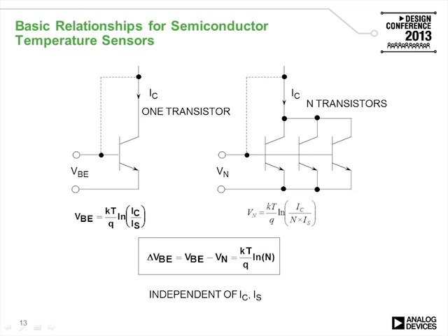A silicon temperature sensor is actually quite a simple device and simply uses the delta VBE, base emitter voltage, which results from the same current flowing through two transistors of different areas. And we can see that that delta VBE is proportional to absolute temperature T over a very wide range. We've gotten these to work down to liquid nitrogen and to well over 200 C.